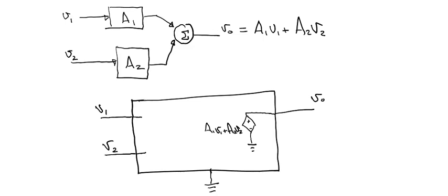A useful amplifier is the differential amplifier. It's used to measure the difference between two usually small voltages. The two input voltages are measured between the amplifier's input pins and ground. And on the diagrams, if you see, they're labeled V1 and V2. The output voltage is an amplified version of the difference between the two input voltages.